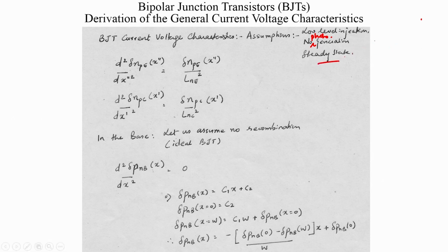So we are in a steady state low level injection condition, and in the continuity equation, this means G is 0. This means I can use my very convenient delta n by tau n or delta p by tau p recombination rate, and any derivatives with time are 0. So these are the 3 conditions and we will throw them into the continuity equation. And of course, the electric field component is not important. So that is another aspect.